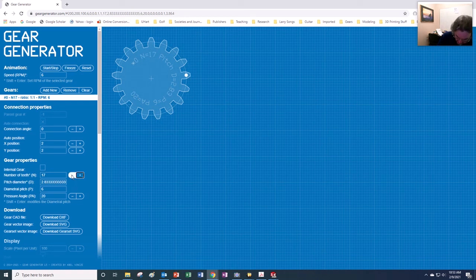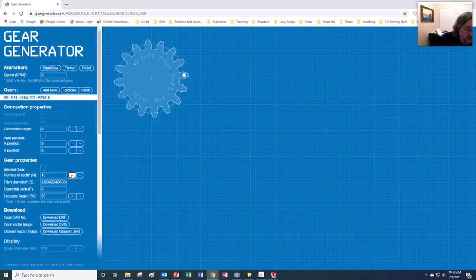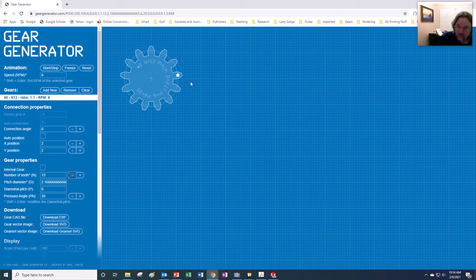For some of the examples, let's say we had 13 teeth, where they were saying that was the minimum number for non-interference, and I have a pressure angle of 20. You can increase the pressure angle, but 20 is standard. It doesn't come in a whole lot of other pressure angles. I think there's 20, 21 and 22, and then 14.5. I don't know if there are that many others. They'd have to custom make them.